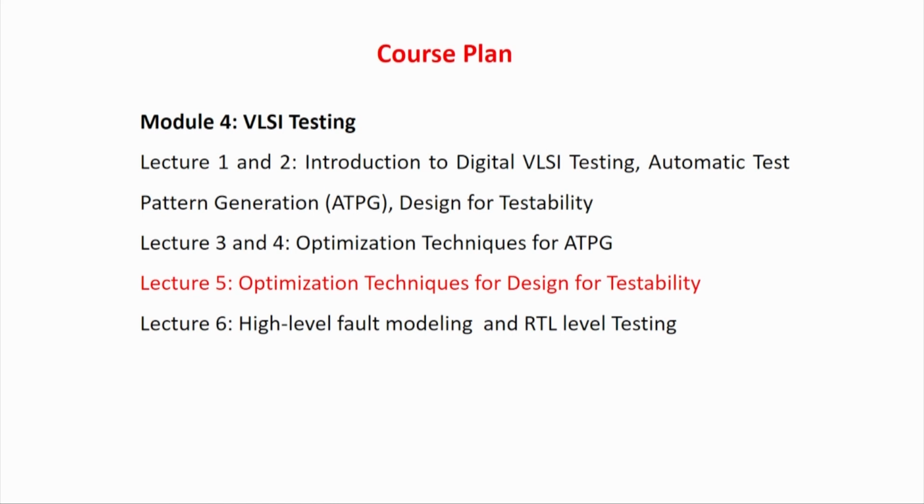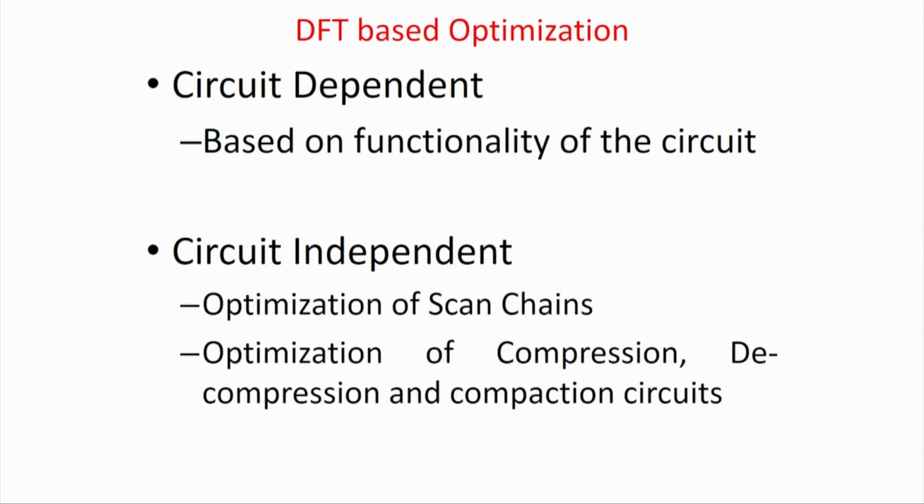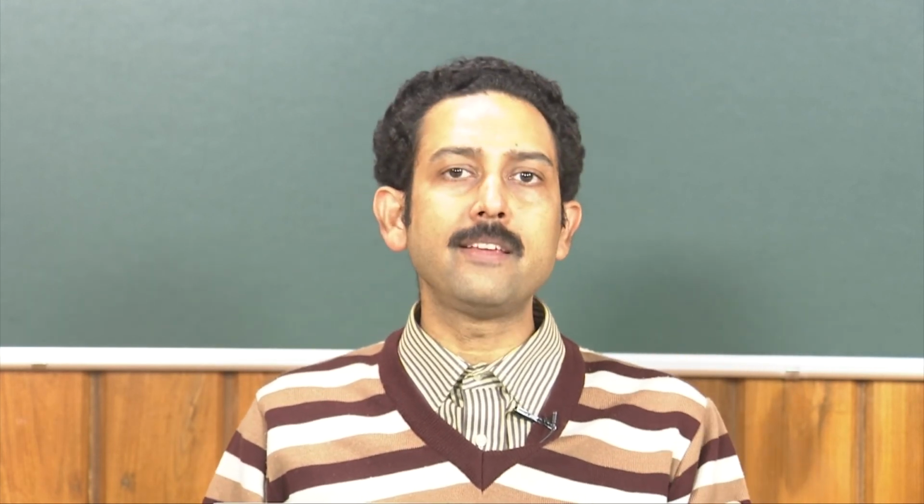For example, to make a circuit testable, we can put a lot of additional circuits so that testing becomes very easy. But adding too much circuitry leads to two types of problems. One is that the circuit cost will rise and power will rise, and at the same time, who will test the circuit which you have put in for design for testability? If the DFT circuit is smaller, we can assume the probability of faults occurring in it is lower, or it will be easier to test.